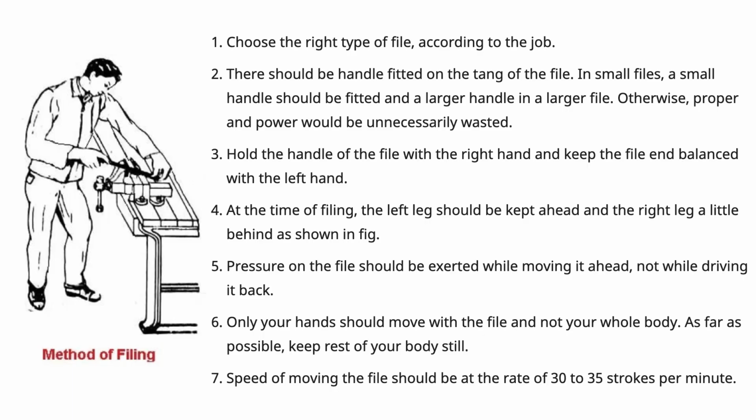For filing of metal sheet jobs, the job should be fixed firmly using wood on both sides, and it should be ensured that the sheet does not stick out higher than twice. While filing a sheet, we should cut it in length. We should make use of chalk in order to save the job from pinning. If there are metal particles on the file, they should be cleaned with a brush. Keep a file away from other tools, and they should not be heaped together. The file should not be heated, and do not apply oil or grease on the file.